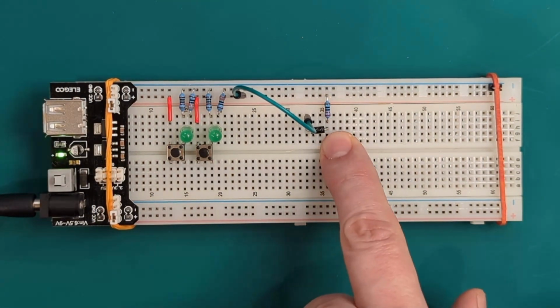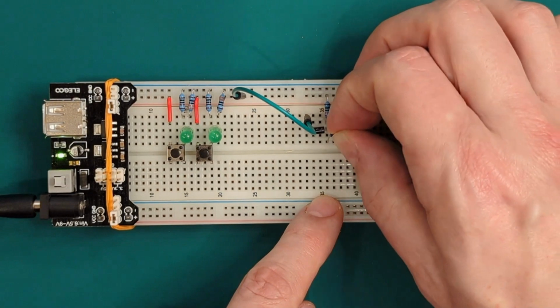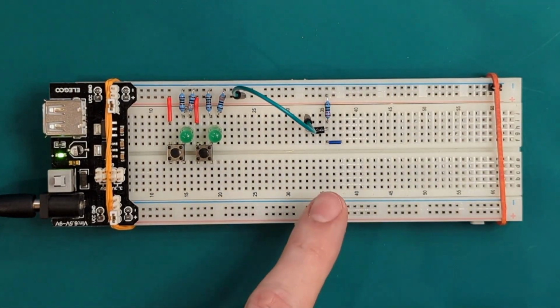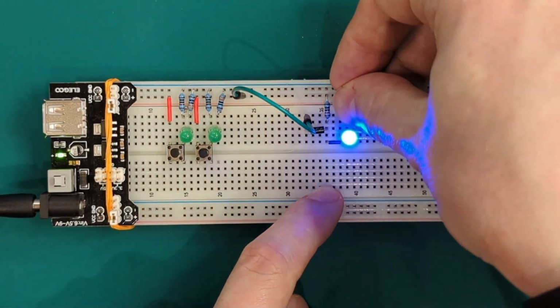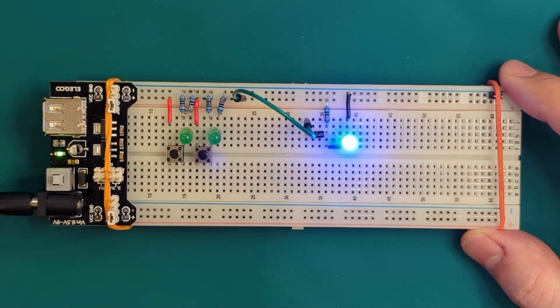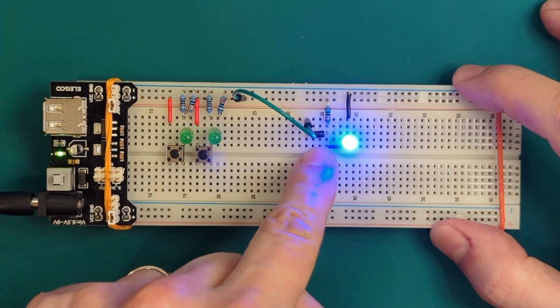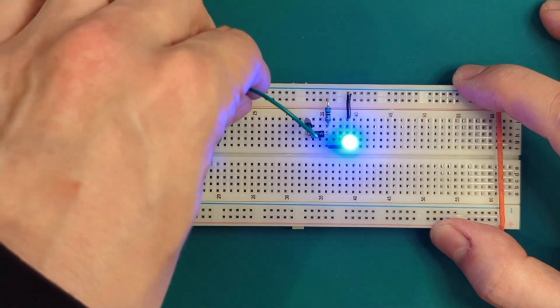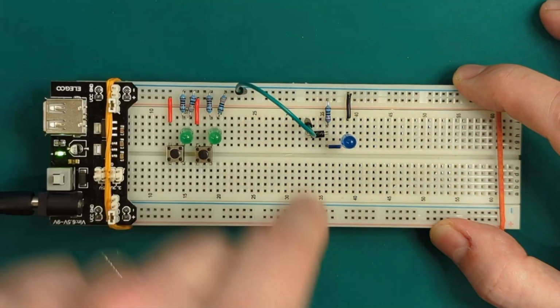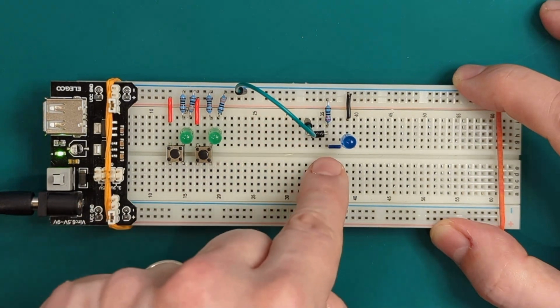So if we call this junction over here the output of this circuit, I can pop a LED there. So let's mark the output as the small blue wire over here and tie this output to a LED that should be connected to ground at the end. When the input is high, the diode is closed, so current flows through the resistor into the LED and to the ground. If my input is low, current flows through the diode directly into the ground rather than going through